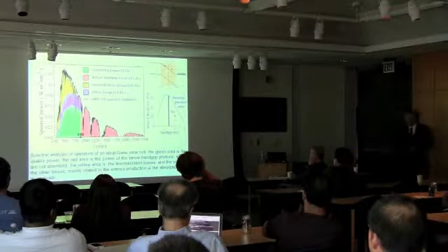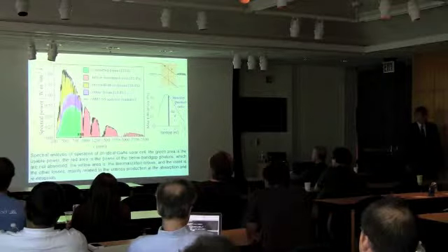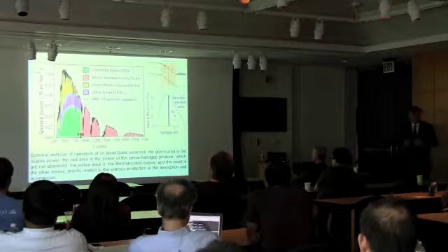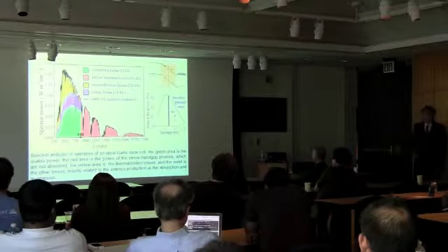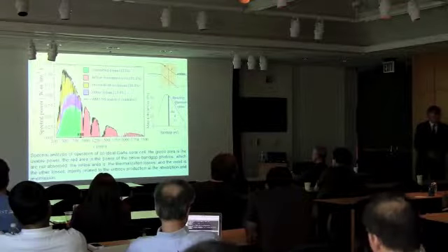Here I show gallium arsenide, so this is 880 nanometers or 1.4 electron volts in the energy. Whatever has a longer wavelength goes through gallium arsenide without absorption. So this is immediately lost no matter what, and these so-called below-gap losses are 33%. So you cannot have your solar cell more efficient than 100 minus 33, because 33 went through already.